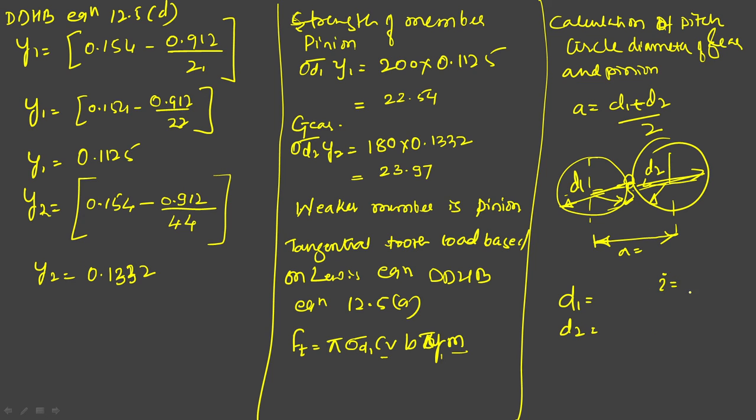As you know the speed ratio here, D2 equal to 2 times D1. So if you go for the relation here, pi D1 N1 equal to pi D2 N2. So what we are going to get here, D1 by D2 equal to N2 by N1 or vice versa. And we can look at this velocity ratio factor. I am directly writing this equation: D2 equal to 2 times D1.